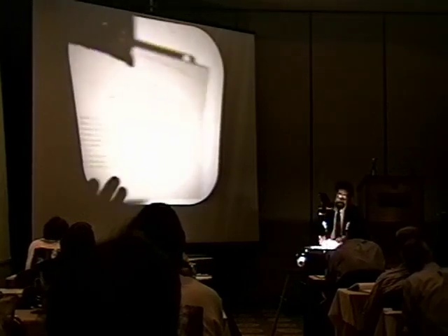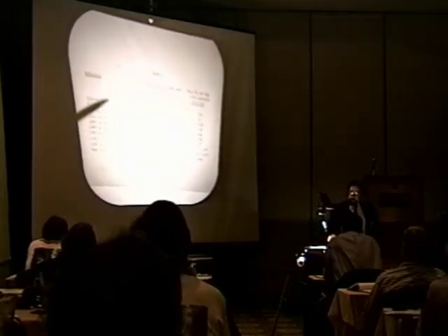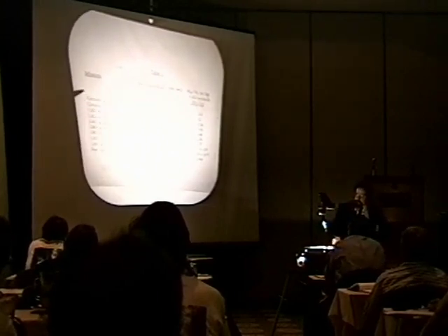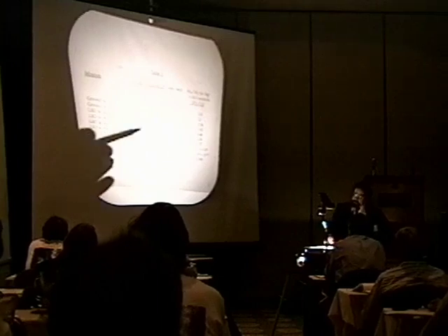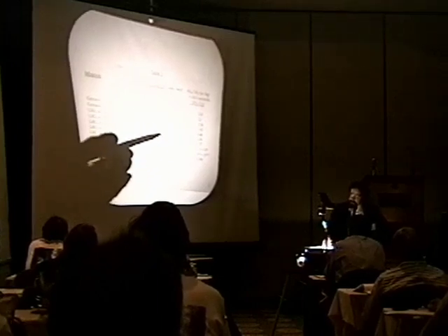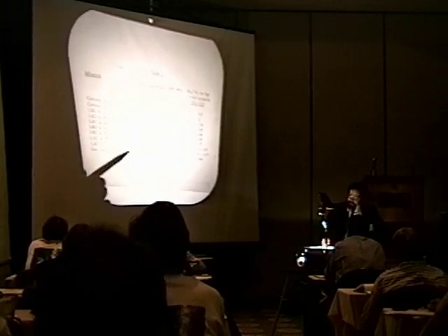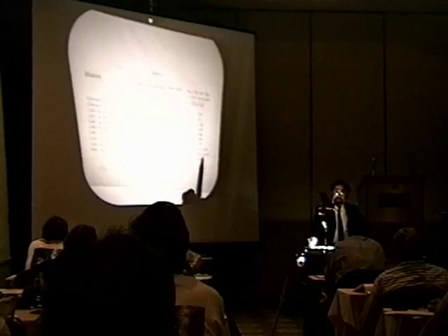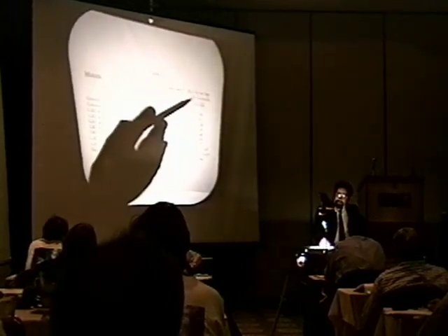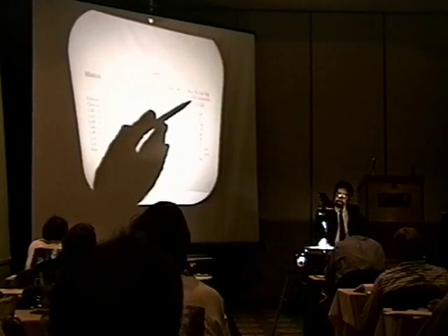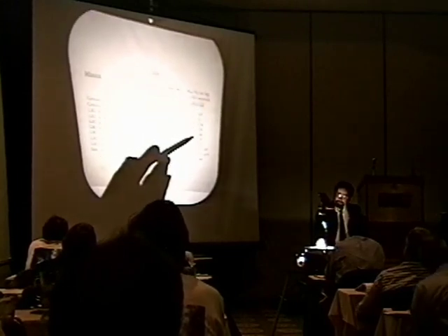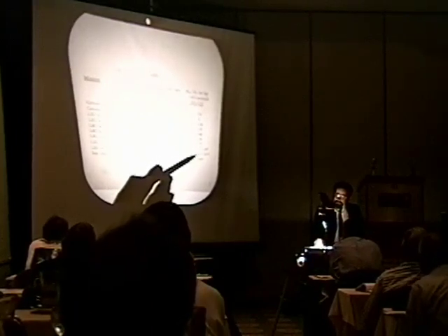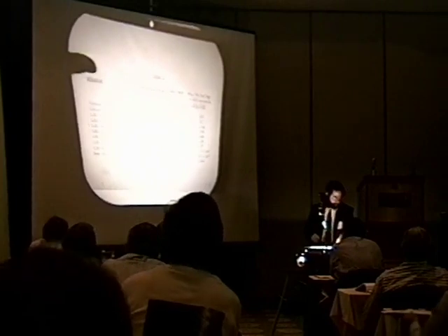Well, this chart just shows you very briefly that there are certain velocity requirements for these various missions, to launch into Earth orbit and to go to Mars and so forth, in kilometers per second. They go much higher when you get into difficult missions. If you're doing it with a single stage in particular, you need very high mass ratios. It's not so bad in this column here with an Isp of 460 seconds, the kind of mass ratios that you need for some of the inner solar system work. But when you really get out into the solar system, a single stage using chemical propellants is impossible to do anything with.